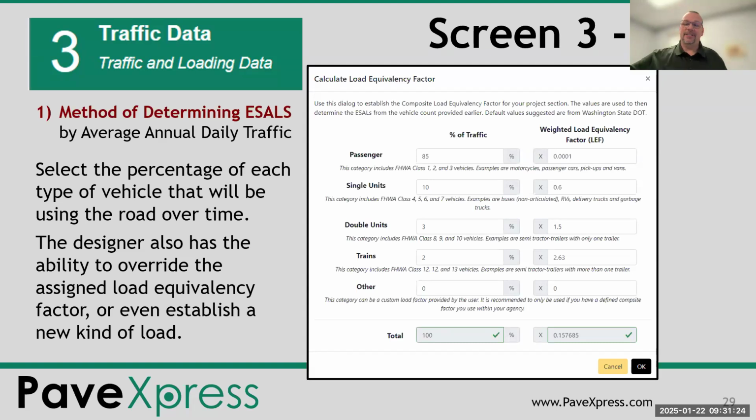If you do know the heavier weights, like outside of an asphalt plant or something, if you're designing a road there, you've got loaded trains of 80,000 pounds, or 80 tons, so 160,000 pounds. And then by the axles, you're probably over that too. So you can calculate out a different load equivalency factor. The big part is knowing what your traffic is.